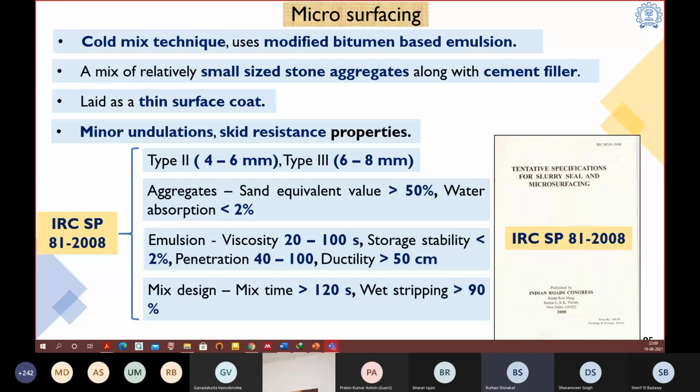So finally, these are some notable mentions as far as aggregate materials, bituminous binders and bituminous mixes are concerned. As far as aggregate materials are concerned, we are also seeing the industry moving towards the use of synthetic aggregates, manufactured aggregates using captured CO2. For binders, sulfur extended bitumen, bio-derived bituminous asphalt binders, and highly modified asphalt binders, which go under the acronym HEMA.